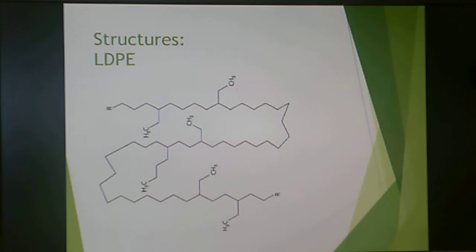This is a representative structure of low density polyethylene. The reason why the crystallinity is lower is because there are these branch points off of the chains. It's these branch points that keep the density of the polyethylene lower. It prevents a lot of the crystallization. So this structure right here can stack really, really easily on top of something that looks like that. But if you put a branch point there, it prevents that stacking, and that's what reduces the amount of crystallinity in low-density polyethylene. Now, when I'm talking about crystallinity among the polyethylenes, I'll say that this has low crystallinity. But when I'm talking about crystallinity between polyethylene and, say, nylon, even low-density polyethylene still has higher crystallinity than a lot of nylons. So polyethylenes across the board are very crystalline of the semi-crystalline polymers.